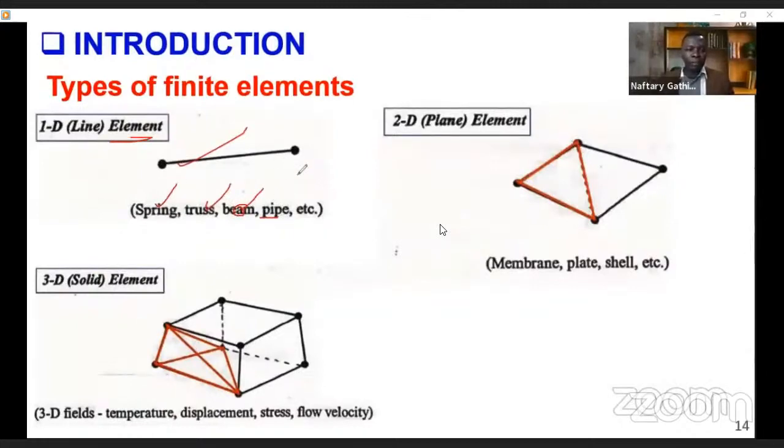And then the beam, we extended, combining two beams oriented in an arbitrary plane to get a frame. But you see, even though the element can be oriented in a Cartesian plane, maybe 2D or even 3D, the element by itself is just a line, right? It might have 2 nodes and degrees of freedom per node, maybe for a beam being 2, for a bar being 1, but still a 1D line element, right?